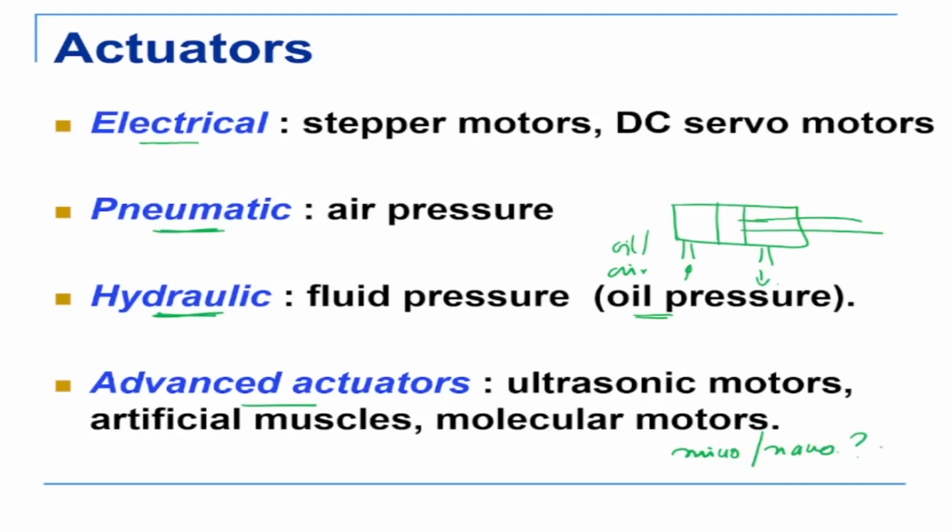So we talked about the electrical actuators, stepper motors, DC servos. Now the important question is, where would you use which actuators? In the case of a robot, very often the base joint of the robot carries the maximum weight. Suppose it is rotating about this axis, it is called the waist or the base joint. This carries the maximum weight, so basically we use a hydraulic actuator there. So which actuator is the most powerful here? This hydraulic one.